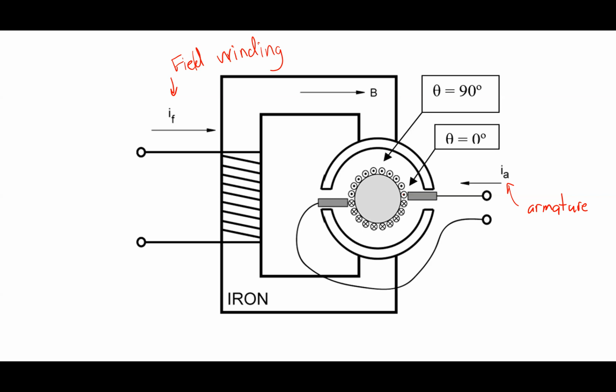So what I have in this picture here, right, is these guys are the brushes, right? And there's a set of copper strips on the shaft that basically direct the current from the stationary world onto this rotating thing. Now, what's special about these windings is basically, and we'll go through the analysis here, so let's see, it's going to be I cross B. Yeah, this machine is going to rotate in a clockwise direction, right, eventually.